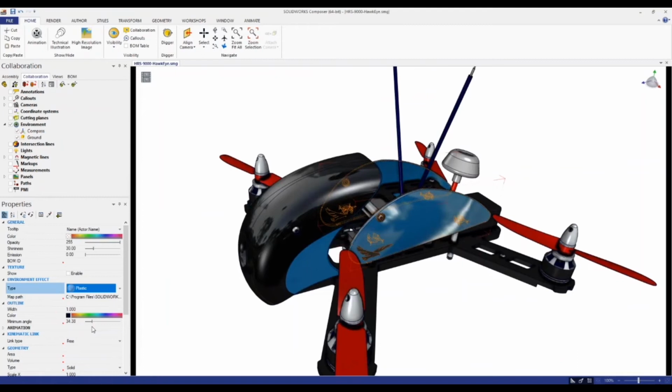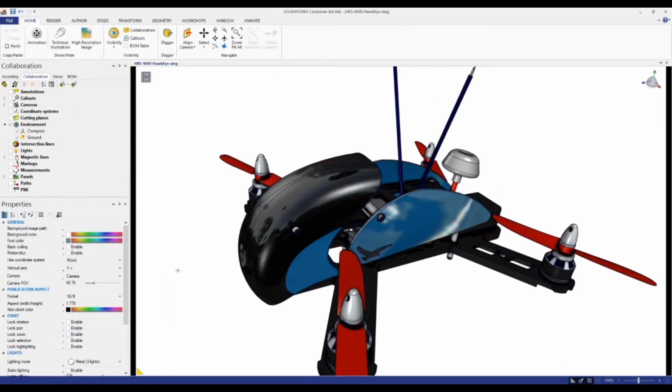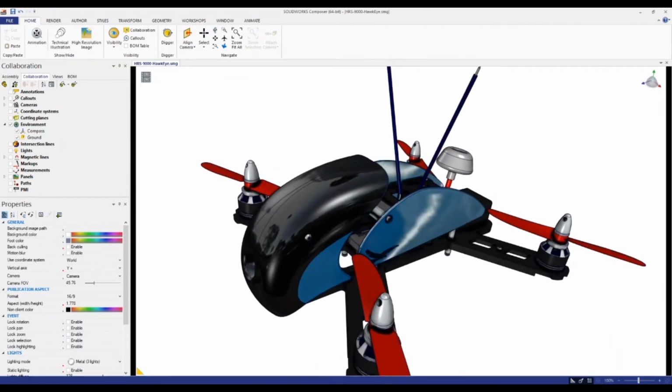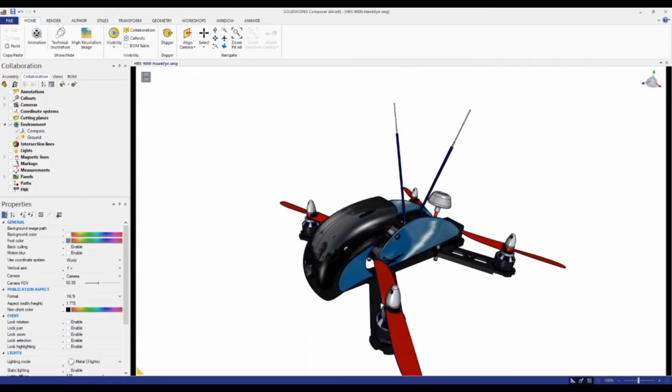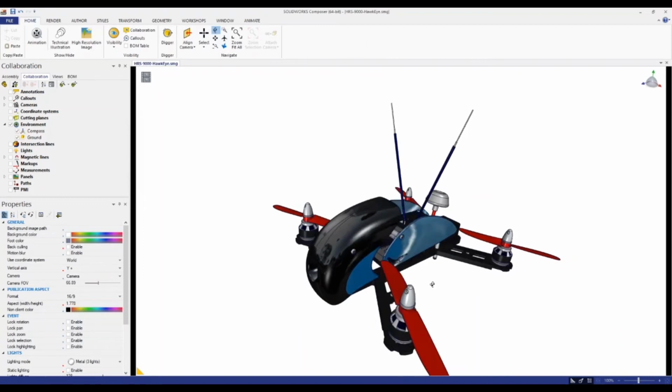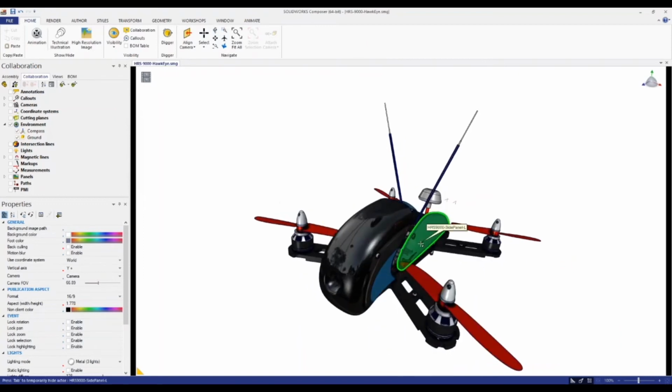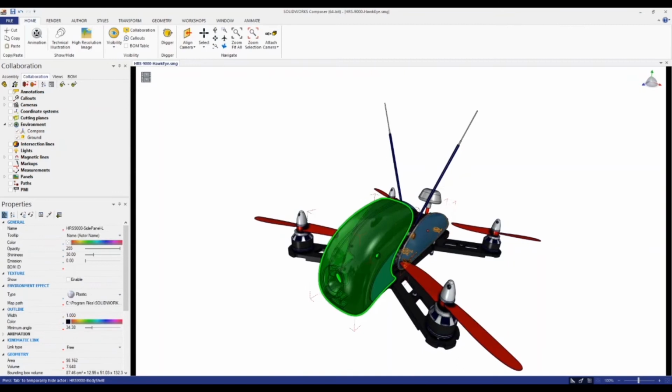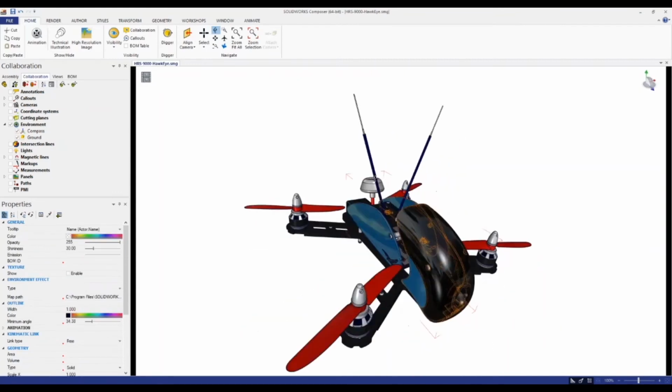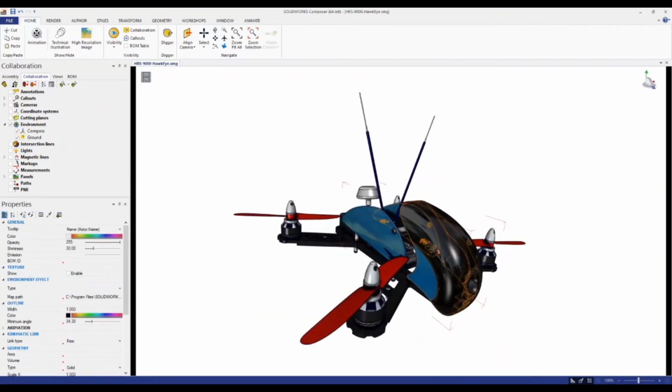So you can choose this, so remember how we changed the entire lighting, but this is now more specific to the geometry we're selecting. And then I mentioned opacity. Well, if you were to do an exploded view, you can see exactly how all this comes together, some of the internal components, but right now we can't. So what I can do is modify its opacity or the transparency. And to do that, I can select them. You don't have to wait for your designer or your engineer to do it inside of SOLIDWORKS and send it over.